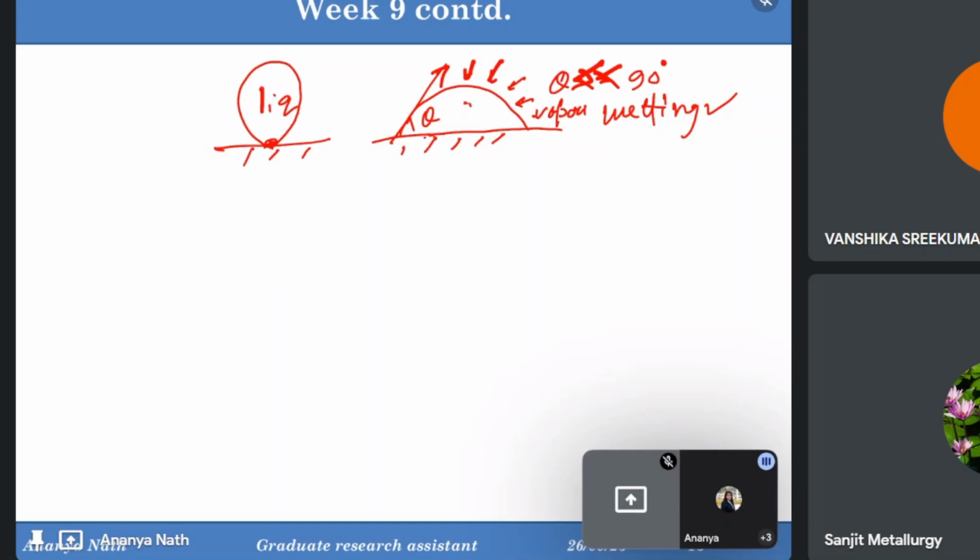Then comes the particle bonding. The load is transferred to the stronger reinforcement via the particle or matrix interface. Therefore, the interfacial bonding must be strong. As I said, whenever you apply some force onto the metal matrix composite, the force will directly attack the interface. It will try to detach the interface or detach the particle seated over there. So the interfacial bonding is very important, and that depends on the wetting and the solidification conditions.